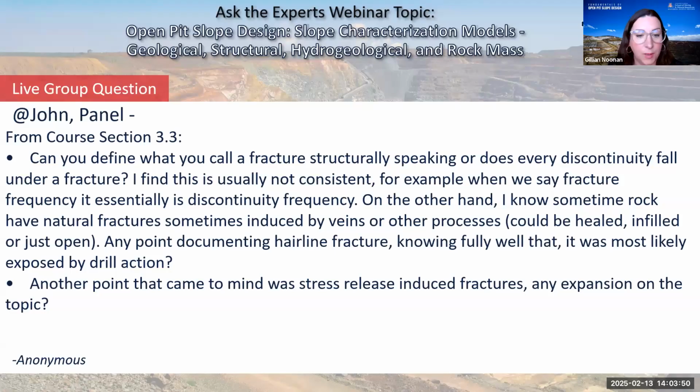Thank you, John. And I'll open up to the rest of the panel if you'd like to contribute. I see Felicia. John, just for discussion, I know when I'm organizing a logging campaign with drill holes these days, I tend to instruct my team, the geologists, not to log what we think are drilling-induced fractures. Or if you're going to give them a different code, don't call them joints, because you don't want to mix them up with the natural structures, because they will have different continuity implications. What do you think?